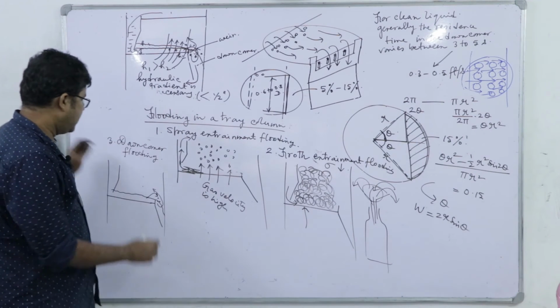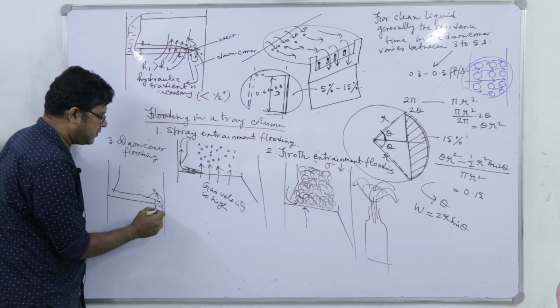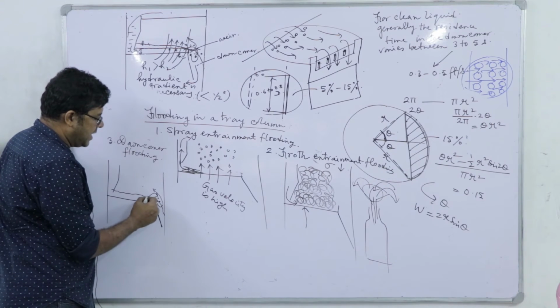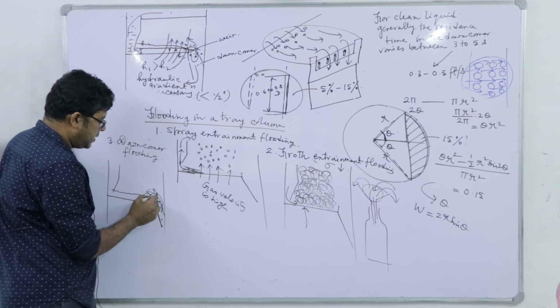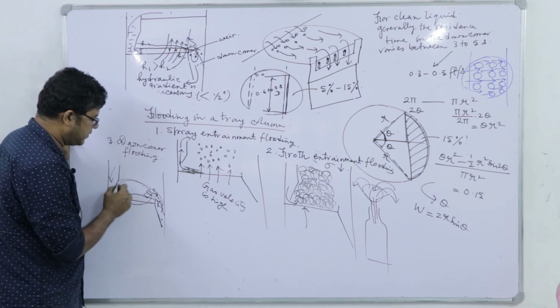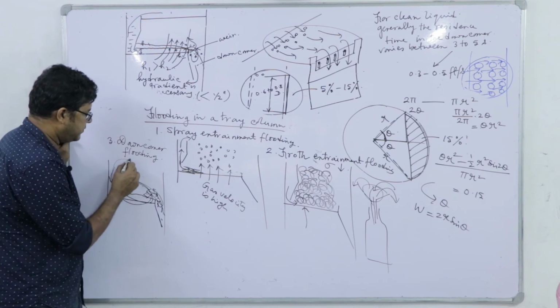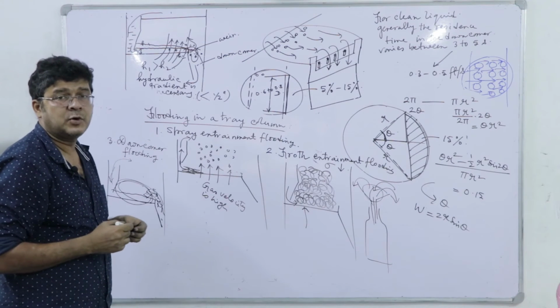right. So, if the liquid flow rate is high and the downcomer area is not properly designed, what will happen? The downcomer may choke and the liquid will flow out, right. But the liquid flow rate is high, so what will happen? The liquid starts accumulating here or the tray above or the tray above. So, in this way the flooding is promoted.